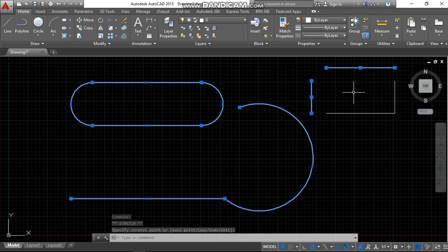And then the difference between the line command and the Polyline command. The Polyline command can be used to draw straight lines and then arcs. And then the line command serves as the constructional lines we use in any other drawing. So you just use it as backup and then you draw your actual thing.